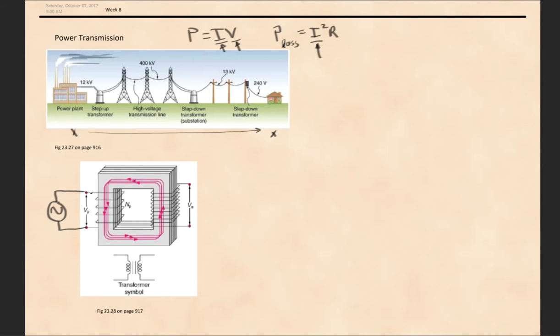Because I've got current flowing through this wire and the current is changing, it will create magnetic fields inside the coils that are changing. Those magnetic fields follow this path through the ferromagnetic material, through the iron, and they pass through the coil on the second side. On the second side, I connect this to my house, or whatever device is using the power, and there will be current flowing in this wire because of Faraday's law.